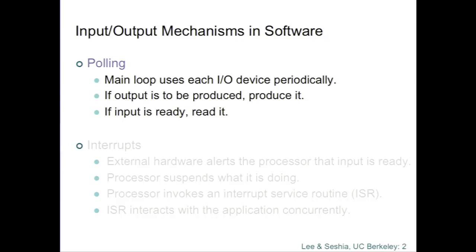Of course, you lose another determinacy property even sooner. A single thread of C is not deterministic with respect to the timing of the program. There are many timings of that execution that are correct. So when you care about timing, you have a little bit of a problem because you're using a programming language that doesn't really allow you to express your timing constraints. And so the timing kind of emerges from the design rather than being part of the design. And that's, in my opinion, one of the biggest flaws in embedded systems technology today, and one of the things that I expect will be changing. Timing will become a first-class entity, and you will have languages that will give you direct control over timing. But it's not there in industrial practice today. And so today, when you need to control timing, you can struggle quite a bit.